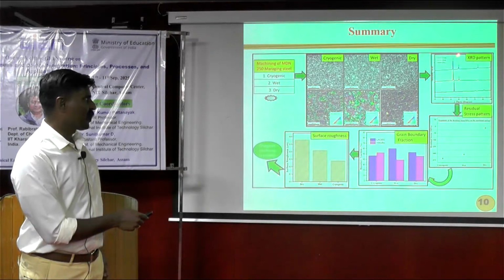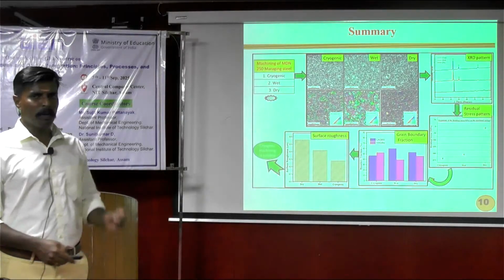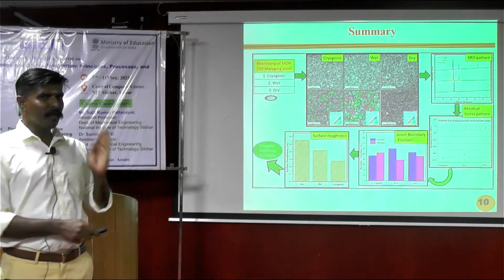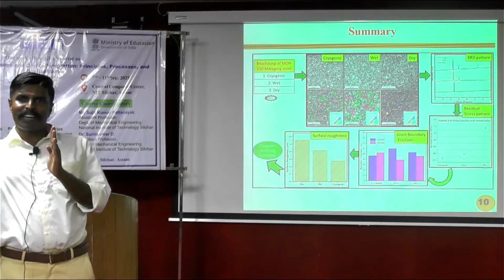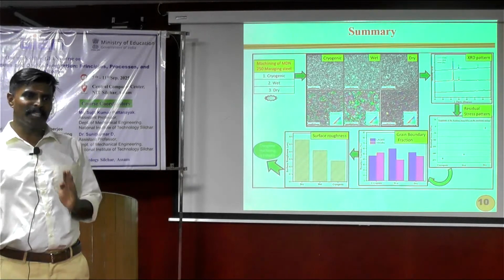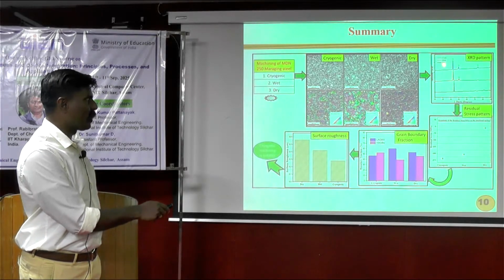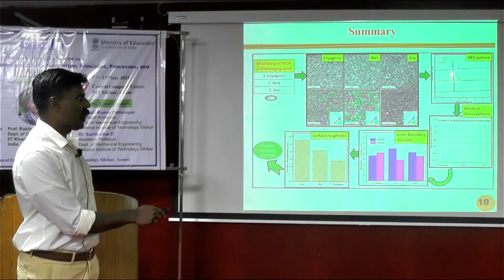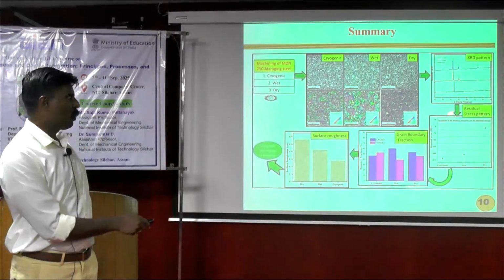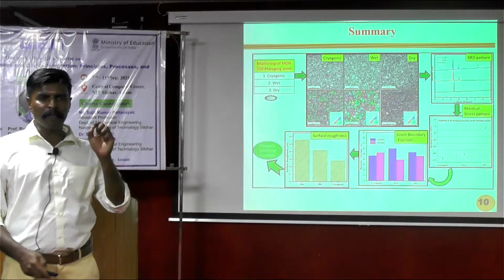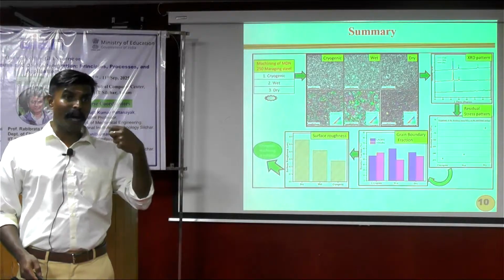Here you can see the cryogenic condition, the blue color peak. Everywhere the peak is there, but if you look minutely, there is some peak shift. A peak shift towards the right side means there is tensile residual stress evolution. You can see this is the peak area. Suppose it is 42 point something for cryogenic, but for the wet condition, the red one, maybe 42.6, and this one maybe 42.8. Like that, there is some minor shift in the peak. That shift in the peak tells us that the residual stress has also altered.